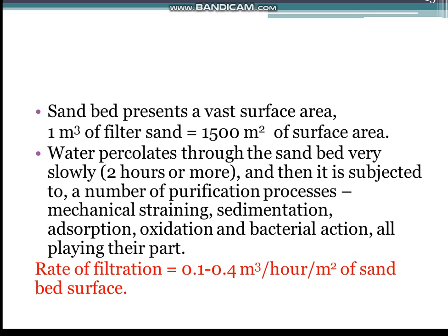The sand bed presents a vast surface area. 1 cubic meter of filter sand presents some 15,000 square meters of surface area. Water percolates through the sand bed very slowly, and as it does so, it is subjected to a number of purification processes: mechanical straining, sedimentation, adsorption, oxidation and bacterial action, all playing their part. The designed rate of filtration of water normally lies between 0.1 and 0.5 cubic meter per hour per square meter of the sand bed surface.